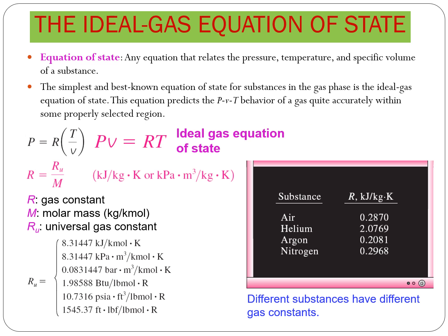It looks very simple. It's important to know what each variable means, and most of the time where you make a mistake is the unit system. So my recommendation whenever you are using the ideal gas equation is to convert all the variables to the basic unit. If you are in the SI unit system, convert pressure to Newton per meter square. Specific volume is in meter cube per kg. And temperature, very important, has to be on the absolute temperature scale. So in SI, it has to be in Kelvin. In the English unit system, it has to be in Rankine.